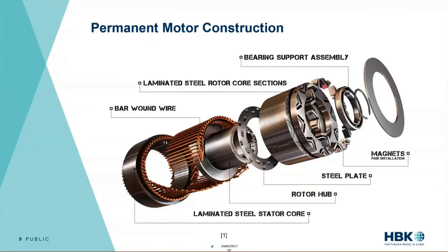And the failure modes we're predominantly going to see are in the bearings, because they're rotating, in the magnets, because they're susceptible to thermal stresses, and in the windings, because they're also susceptible to thermal stresses. So those are the three topics we're going to touch on today.